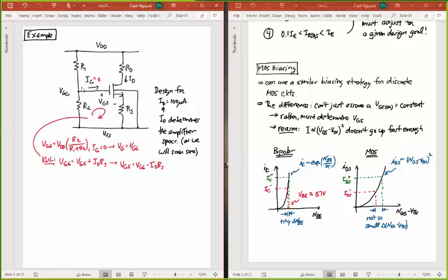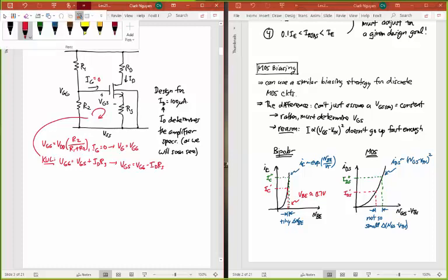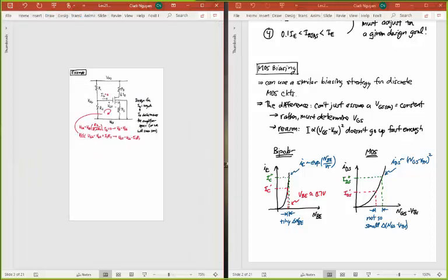I did a bit of Kirchhoff's laws here, and I actually didn't really have to do a lot of this for the design problem, but I did it mainly because I need this for the operating point determination problem that I'll do later on. But for the design problem, I'll just start writing equations that dictate this current, ID, flowing through that transistor. Let me switch to a different color while I do that. Let's write the equation for the drain current.